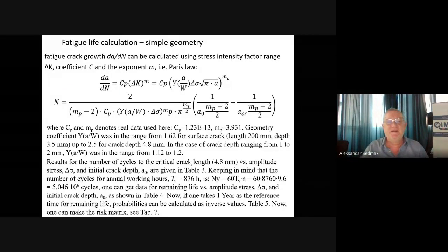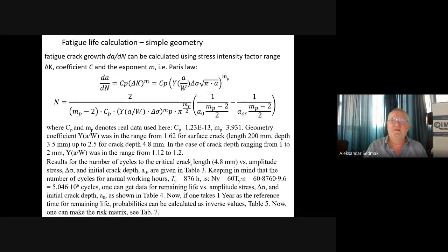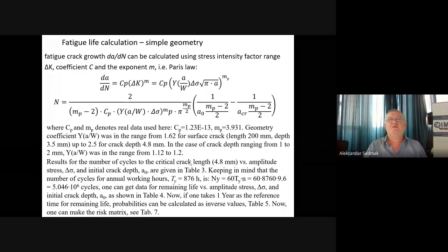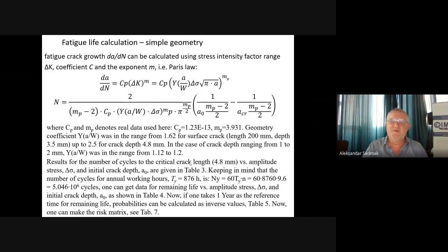But for fatigue, we always have to be careful. We need to check crack length depending on number of cycles, or we need to check what is the spent life in comparison with the total life. So this was done also here